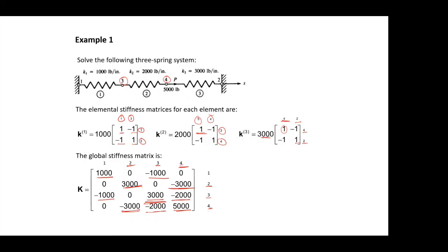Globally, yes. So this load vector, I'm going to write the load vector. You still have F1, F2, F3, and F4. I mean, we still have this same order. The first entry in your vector is 1. The second entry is 2. The third entry is 3. You cannot have the third entry to be 5, right? This is unreasonable. So F1, you go back to the system, and F1 is the force allocated to this node here. Look into F2. F2 will be here. F3 will be the force coming from this node, and F4 is the force coming from this node.